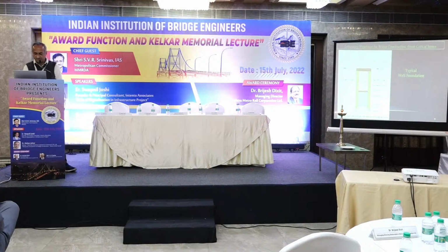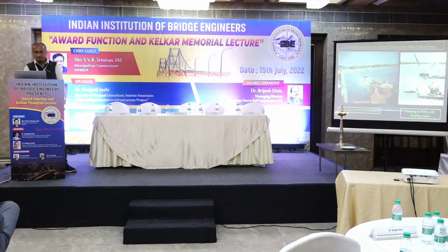There are well foundations in Gangetic plains particularly, where the founding strata can be as deep as 50 to 60 meters below the bed. So a well foundation is the norm in that area particularly. Wells can be constructed in shallow water by just filling up the water body by constructing a sand island, maybe up to a depth of 4 or 5 meters. Then there are barges which support the crane which is sinking the well or doing the mucking operation.